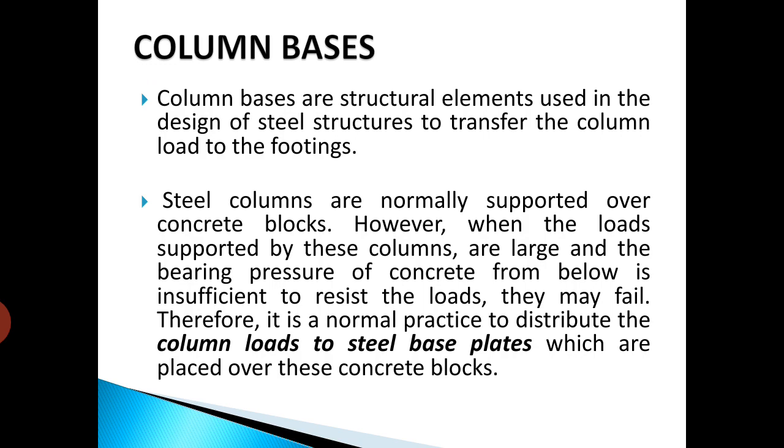However, when the loads supported by these columns are large and the bearing pressure of concrete from below is insufficient to resist the loads, they may fail. Therefore, it is normal practice to distribute the column loads through steel base plates which are placed over these concrete blocks.